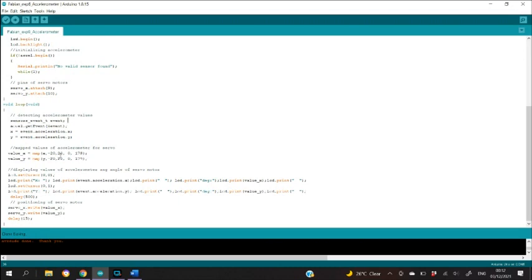We can see we map the x values, ranging from -20 to +20, to 0 to 179 degrees, since our servo motor only does 180 degrees, while the value of y is mapped with the same range from 0 to 179, but instead of x we use the value of y, or the values along the y-axis.